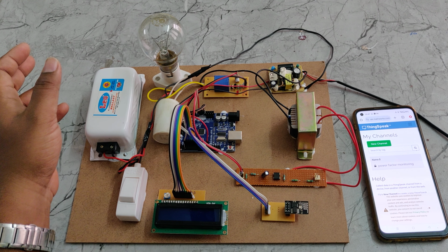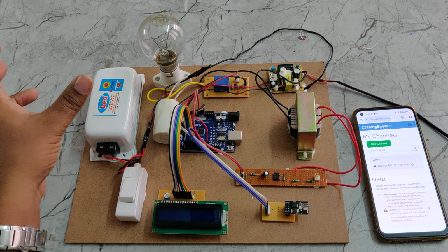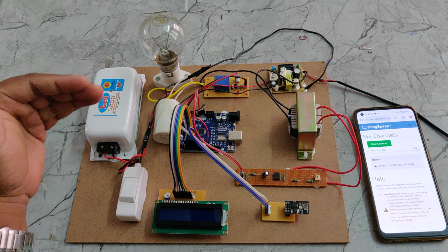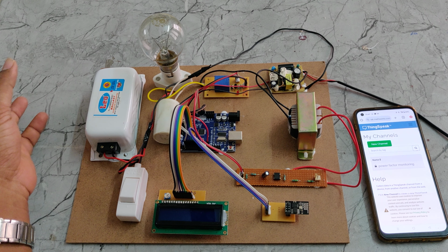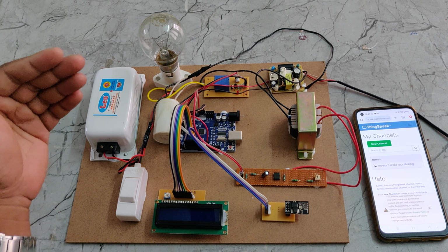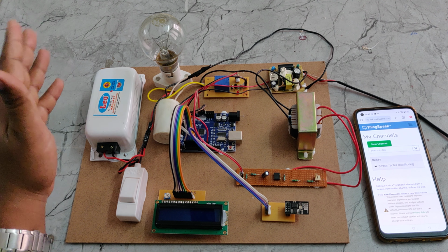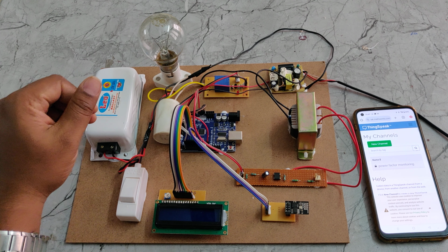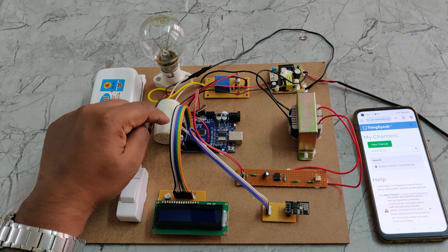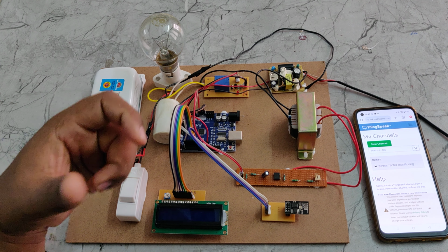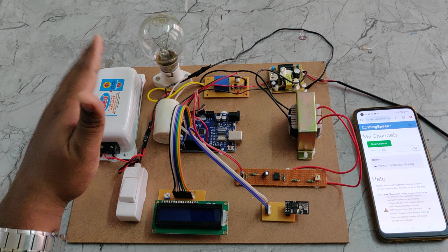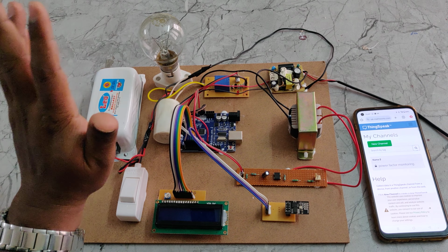Due to that, there is a loss of power, energy is wasted, and we get unnecessary power wastage, and an extra current bill also occurs. So in order to compensate that power factor, we make use of a parallel capacitor. The shunt capacitor will be added in parallel to the L or L plus R load.